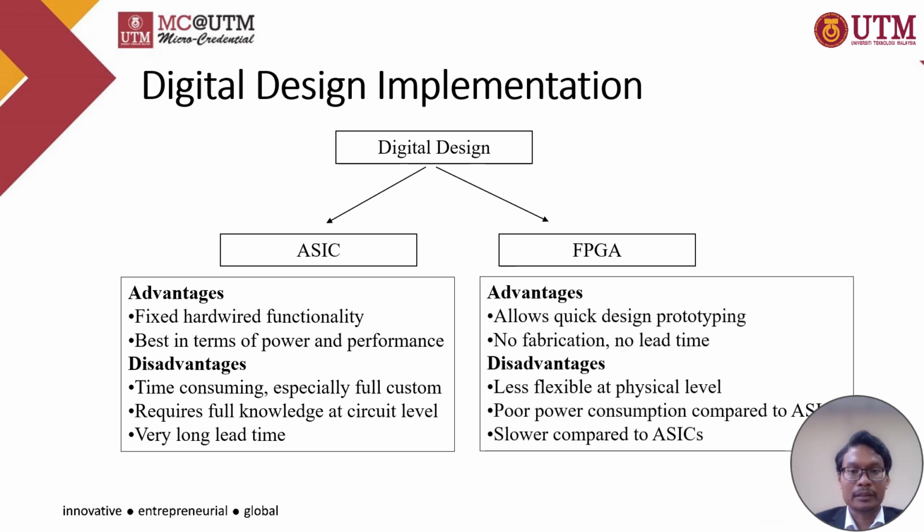As for FPGAs, the main advantage is that they allow quick design prototyping and do not require any fabrication and lead time. However, FPGAs are less flexible at the physical level and therefore result in poor power consumption and lower performance as compared to ASIC implementations.